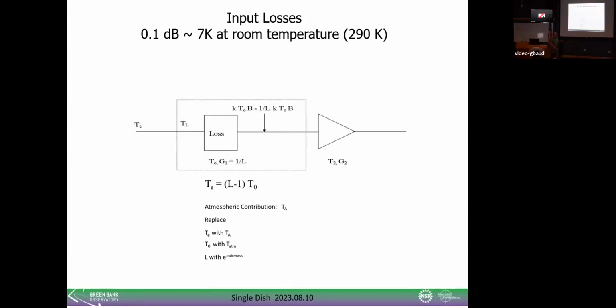So you have to have a component before the amplifiers that allows you to observe both polarizations, and each polarization has its own gain and IF channel. And sometimes you want your receivers to be in native circular mode, so there's a polarizer. All these components before the amplifier raise your system temperature, so you want to have those cooled too.